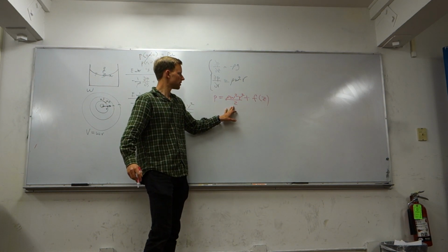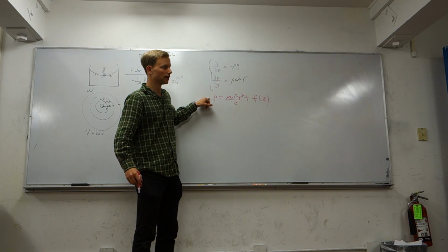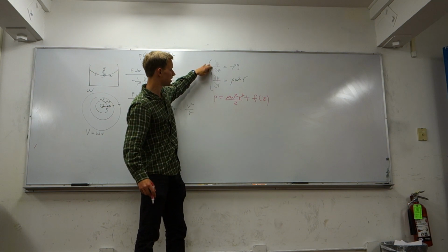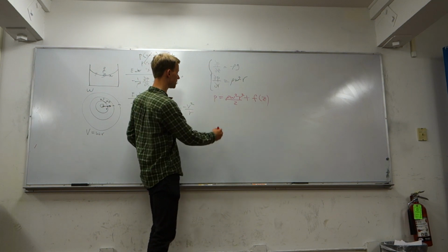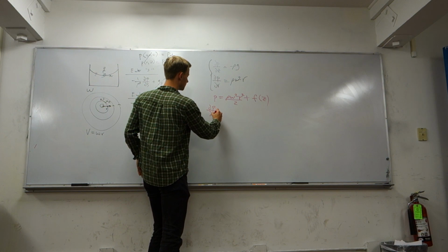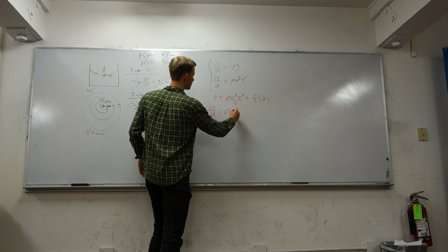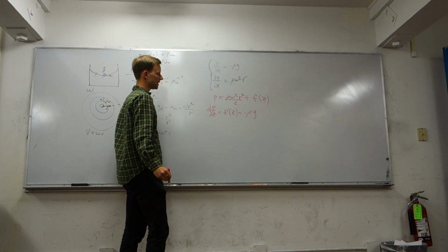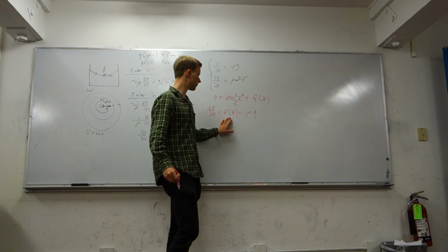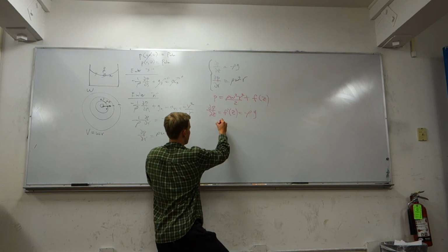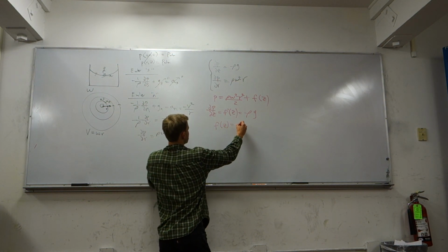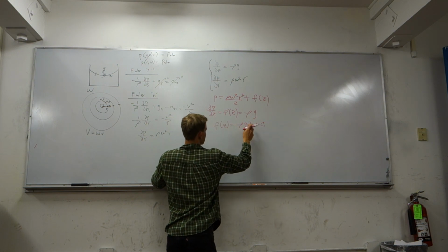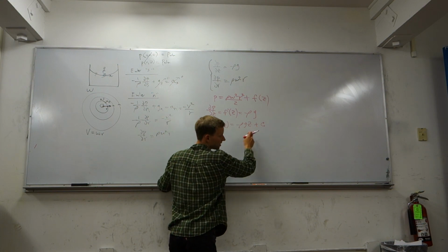But anyway, so now if I differentiate this in z, I'll get an expression only in terms of z, and we already have that expression by our first partial differential equation. So dp/dz is just f prime of z, which we know is negative rho g. And so this is an ordinary derivative, so we can solve for our function f, and we have f of z is negative rho g z, and now we add a real constant c, since this is an ordinary derivative. We don't know what this constant is yet.